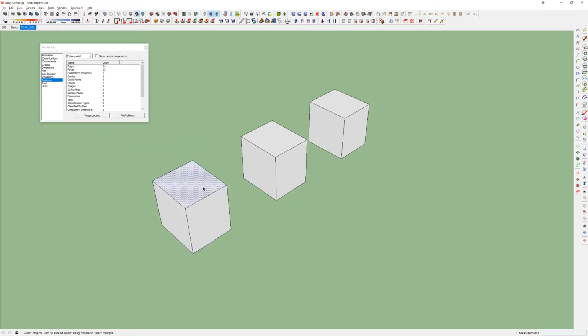Yeah, so then, from this, I think everybody knows, if you left click on a single face, it selects the face. Left click on a single edge, it selects the edge. And there are some additional selection options. If I double click a face, you can see that it now selects the face and every single binding edge. Do you see that? So one click selects the face, double clicking selects face and edges. And if I double click an edge, it selects that edge and all the faces that attach to it.